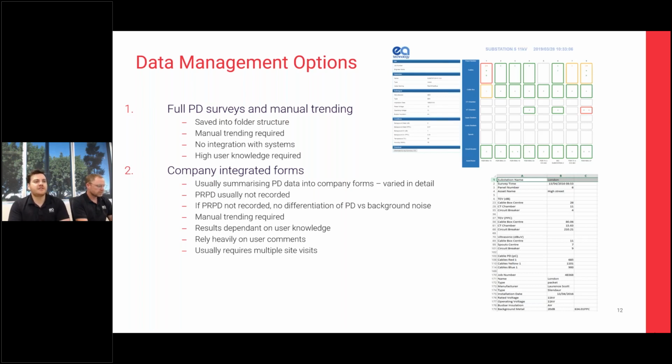So this method does rely on the person in the field knowing how to use the device, but also how to test specific types of HV assets, what test types are useful on different types of switchgear, as well as what test methods are useful to find different defects. Whilst it is a very effective way of trending the gear, it is something that we've been actively working on improving over the years.